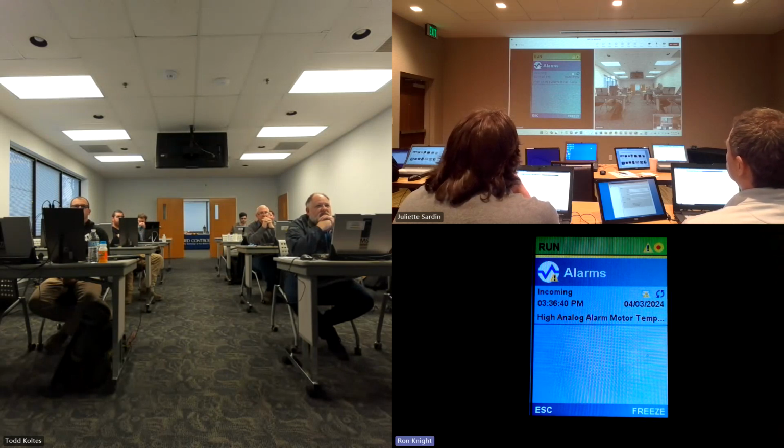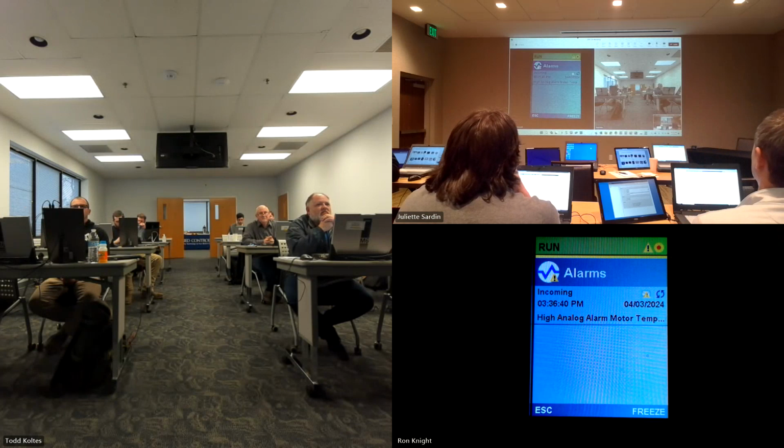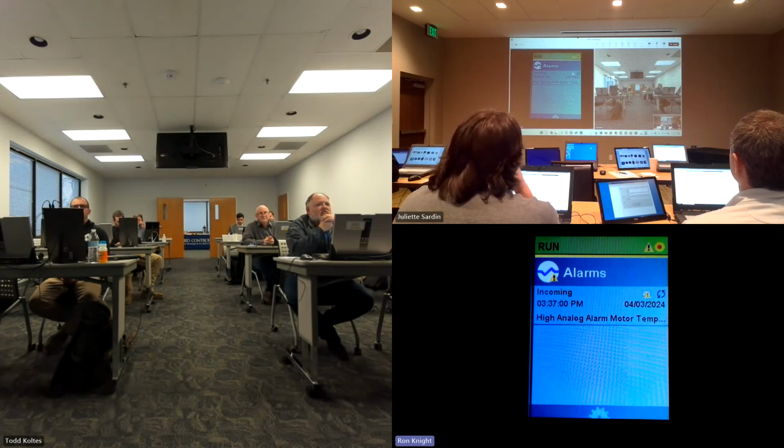And so I've got a high temperature alarm. I've got a process simulation running in here, so I can get process alarms from here. I can get diagnostic alarms from here. So if I lost communications, let's say to an IO module, I can get that out of there.